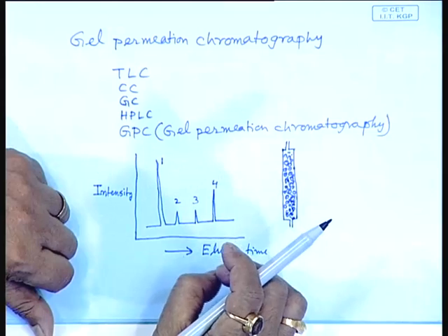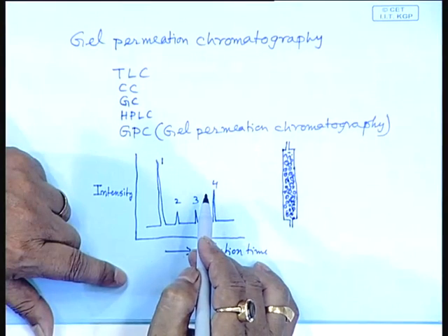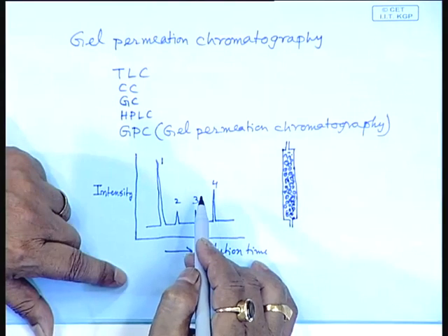Now, if you have a calibration standard, you take one polymer of known standard molecular weight. First, you have to run the GPC with the standard polymer of known molecular weight and plot a calibration curve. Based on that calibration curve, you can know the distribution nature of your test polymer solution, of which you want to measure the molecular weight. So, this is the basic thing done in gel permeation chromatography. In fact, the molecular weights of the majority of polymers are verified or measured by GPC, because absolute molecular weight determination techniques may not be accessible to everybody.